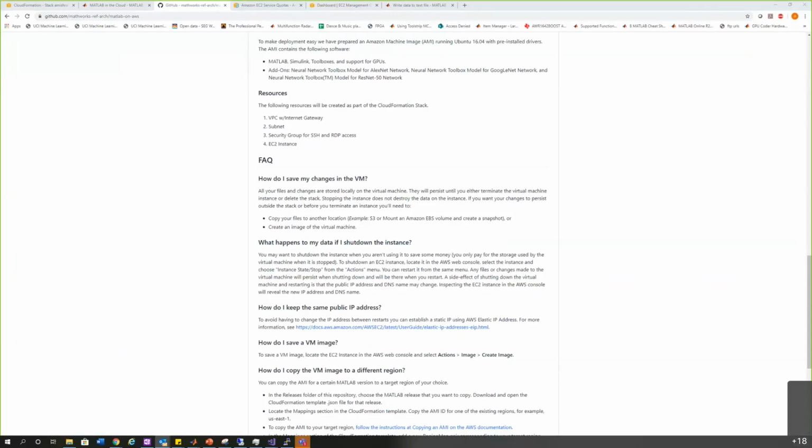On the other hand, with GPU coder, no matter how many filters or how complex the logic you use, because it's still happening at the operating system level, we can generate code like CUDA code really quickly, automatically, and within a few clicks of a button you'll get the optimized CUDA code. So it's a lot easier that way. But yes, FPGAs are still a good tool of choice for most of the DSP industry where the data rates are very high because of the massive parallelization it offers. But the time to market is pretty long for those things.